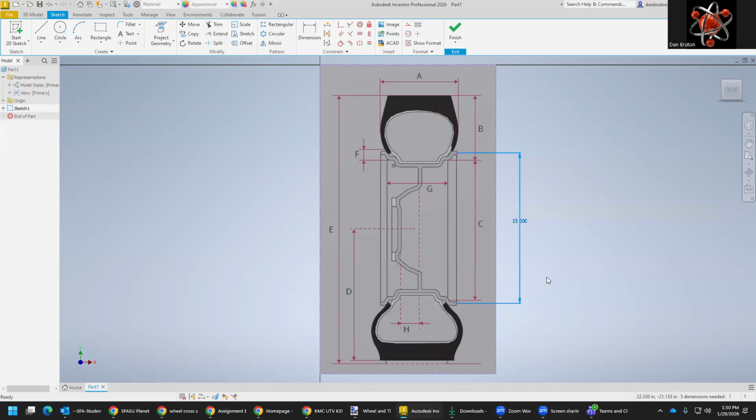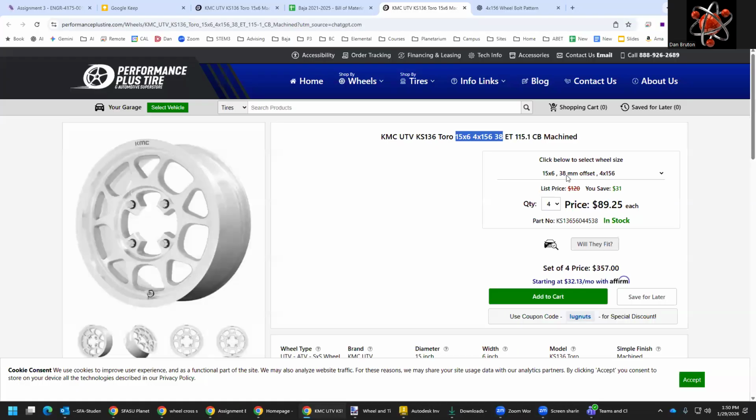Let's draw in some key elements for this that we can use before we start to delete our sketch, because we do eventually want to do that. This is just used as a template. All right, so I would say we need to have a horizontal line for mirroring or rotating, let's say revolving around the vertical axis. And so let's put that in, and we will start from right here at this edge over to that edge right there. Now, eventually we need to change this so that it's going to be 6 inches. Is that right? Yeah, 6 inches.